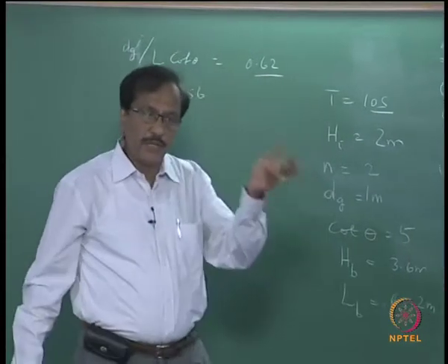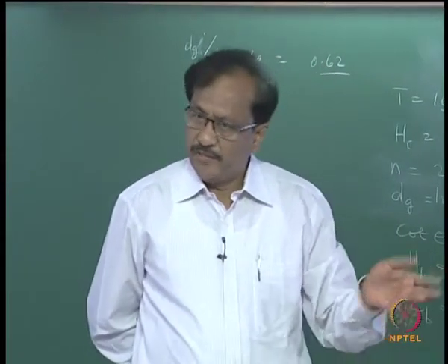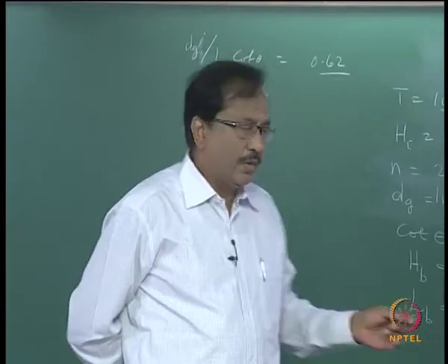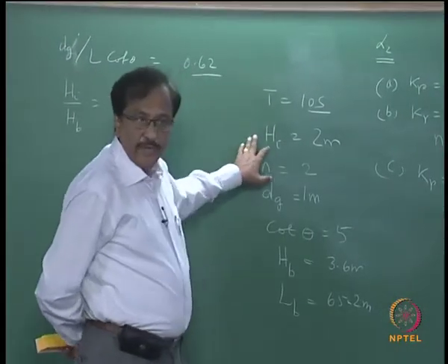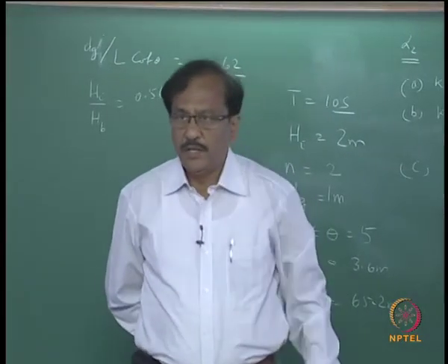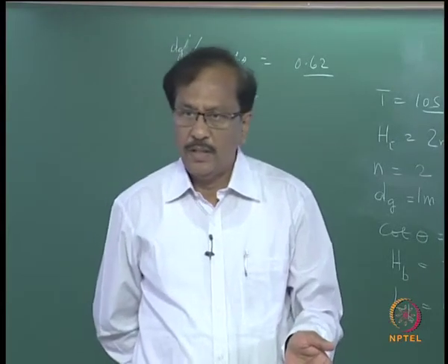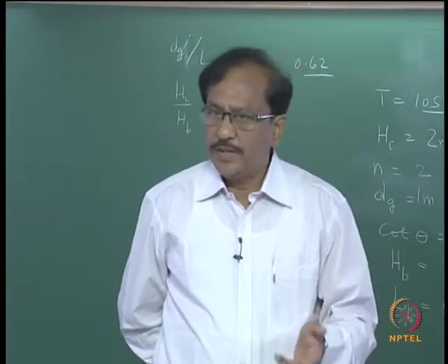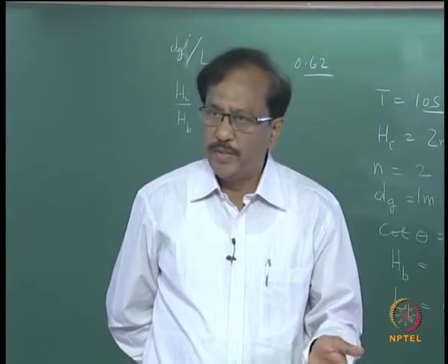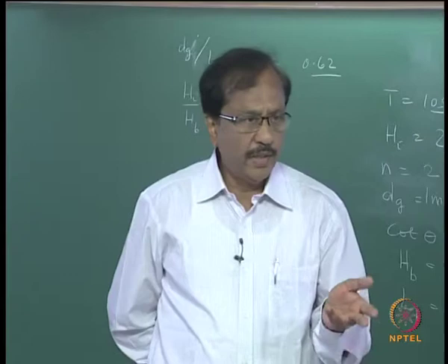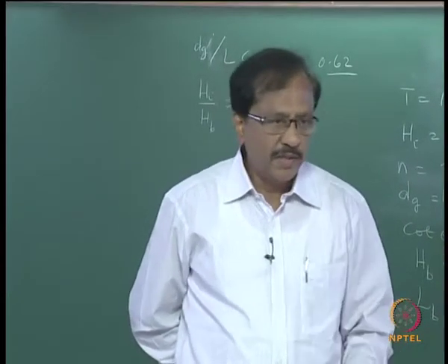Now look back at our discussion on wave deformation. If you know the beach slope, wave height and wave period, you can calculate your breaker height on your own. Similarly, once your breaker height is known, your breaker depth can easily be evaluated, you have all the empirical relationships, and from that breaker depth you can calculate LB.